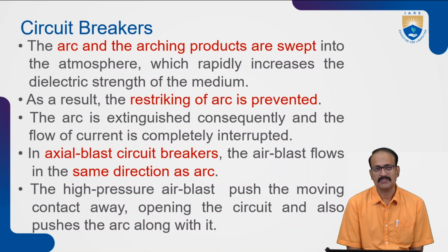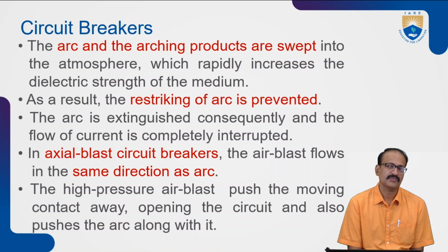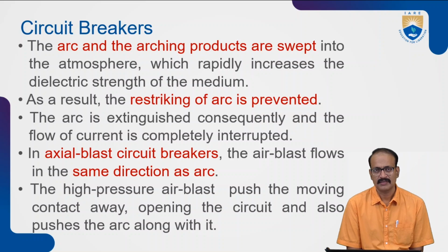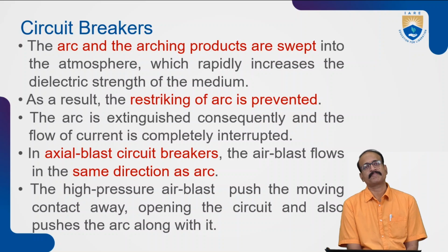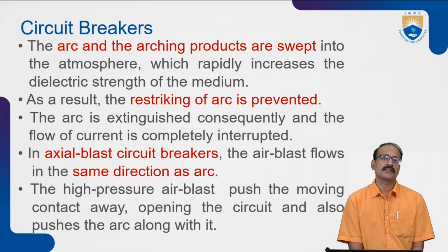These minute materials which are causing and supporting the arc will be absorbed by the atmosphere or the air. But if there is a restricted, confined medium like an oil circuit breaker, these particles will stay there.